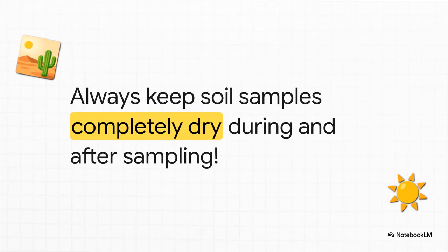Which brings us to our final stretch, Section 5, handling your soil samples. You've done all the heavy lifting out in the field. Now we just need to make sure the lab gets exactly what they need. For your standard composite samples, the name of the game is keeping them dry. You've got to avoid sampling in moist areas altogether. And more specifically, ensure you air dry your samples to protect them before they even get to the analysis stage.